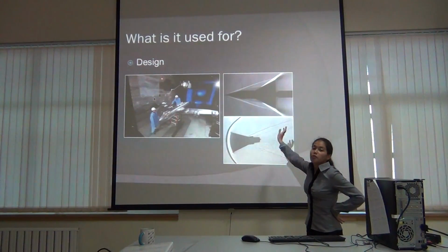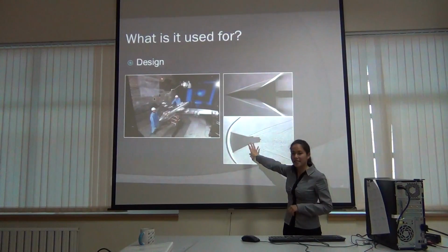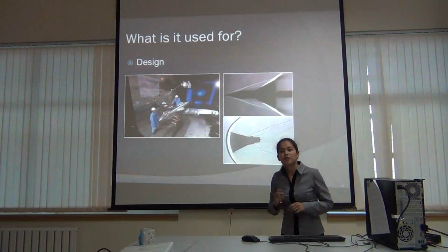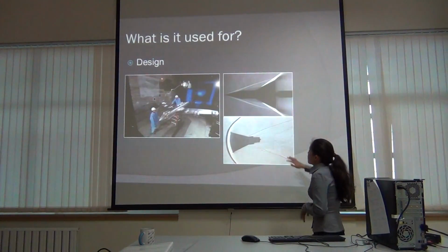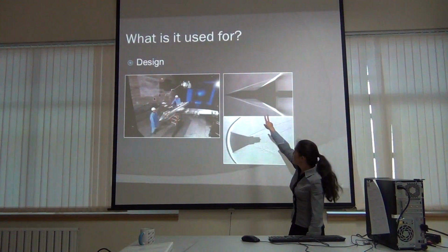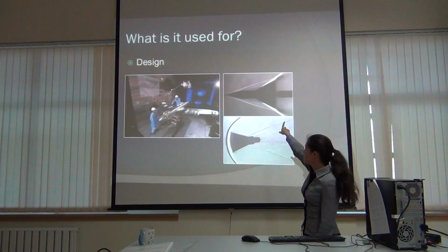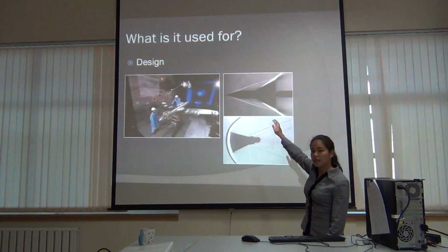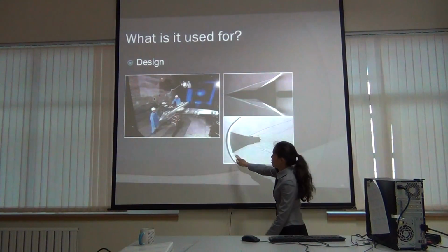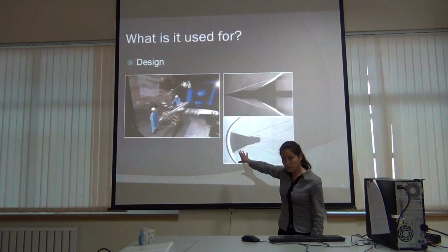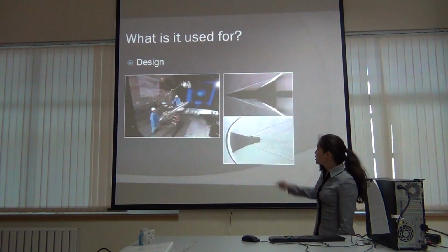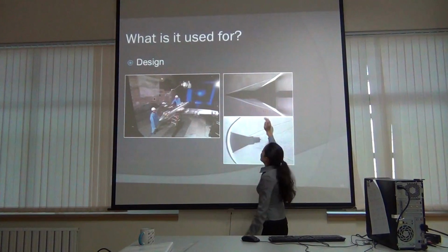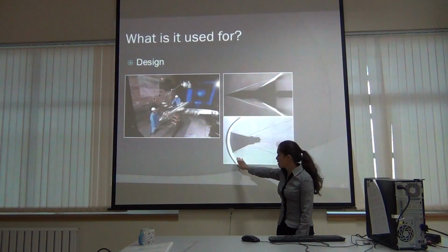If you pursue aerospace engineering, you will learn a lot more about this later, but for now just believe me. When objects travel with speeds greater than the speed of sound, shock waves occur. In the first example, you see that the object is sharp-pointed and the shock wave is attached to it. That makes this shock wave weaker than the other shock wave that occurred here with the blunt shaped body. So in the first case, the temperature behind the shock wave, that is here, will be lower than the temperature behind this shock wave.